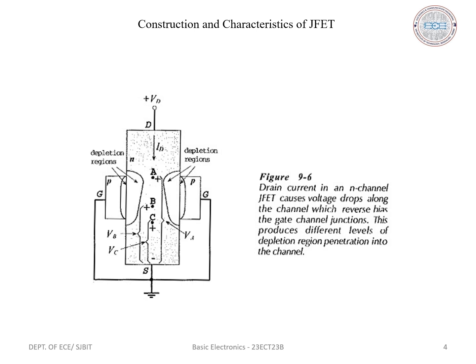These differ from BJT in two respects. Well, BJT is a current control device, but FET is a voltage control device. And also, this voltage control device gives an extremely high input resistance. BJT is bipolar while FET is unipolar, which means that only one type of carrier participates in conduction. FET can be used in amplifiers and switching circuits similar to BJT transistors.